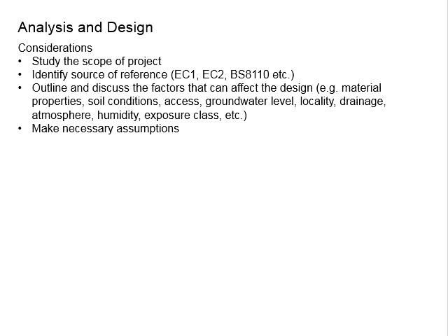As far as the design is concerned, you're going to refer to the Eurocode, EC1 and EC2. For analyzing the loads acting on the slab and beam, EC1 and EC2 do not provide any provisions. Under such circumstances, you can refer to the BS 8110 for the analysis part.